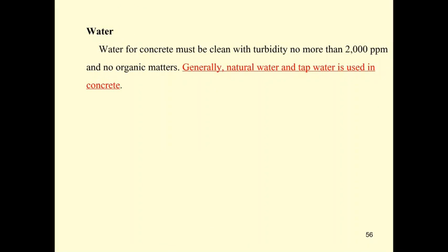The water, in general, must also be clean. Okay, must be clean with TDS no more than 2000 ppm, and especially no organic matter, no fish, no plants, nothing in the water. Okay, natural water is good enough, and tap water is best. Okay, if you stay inside the city, you can use tap water in your mixing.